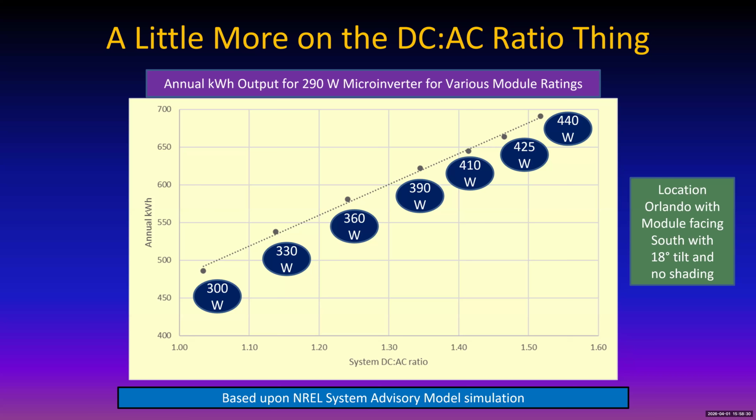Less than 1% difference between the lower power and the higher power. So therefore, it's basically saying that for the most part, the system does not run anywhere near having full sunlight directly shining on the module. And if it is directly shining on the module, usually that means it's going to warm up the module and it's going to run at lower power, as you saw from that graph way at the beginning.